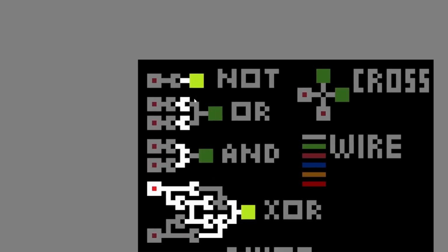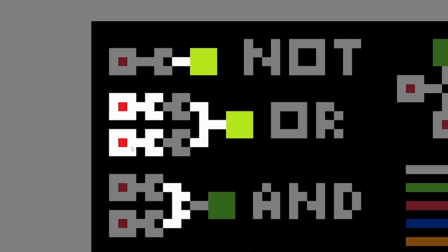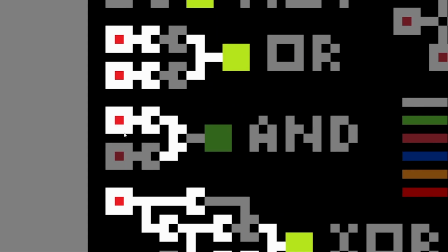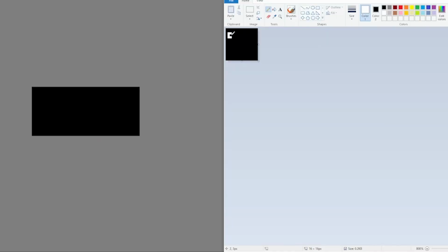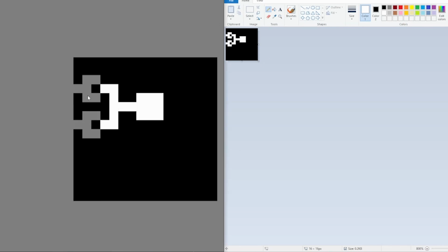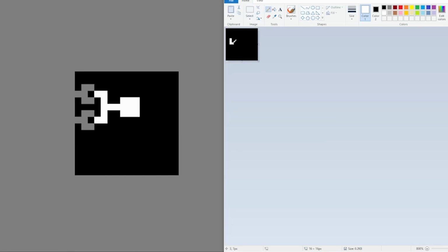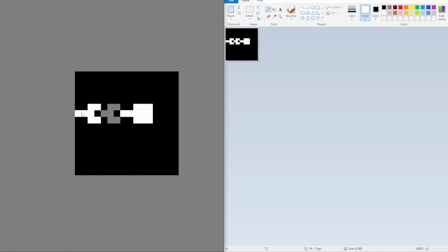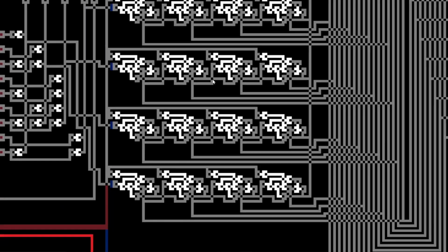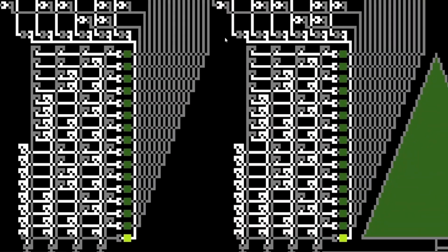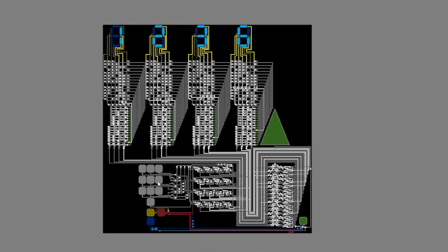You need to recreate all the components that you need in your logic circuits to use them. It doesn't have a floating state, so you can connect 2 NOT gates like this. That way you can have a NAND gate. If you want to make a diode, then invert the signal 2 times. And if you connect 2 or more diode outputs together, you will have an OR gate. You can create with those parts all logic gates, latches and flip-flops, multiplexers and decoders, etc.